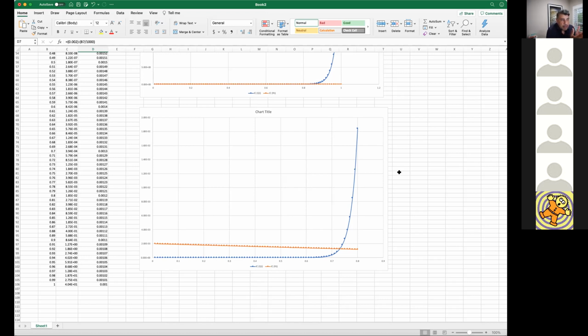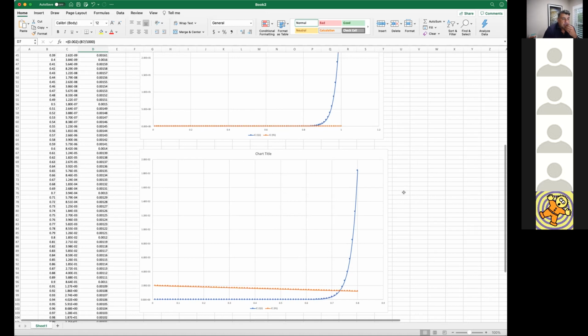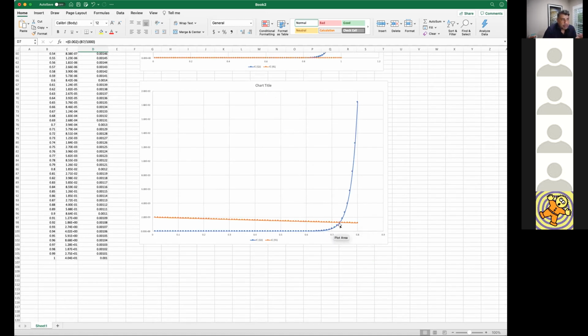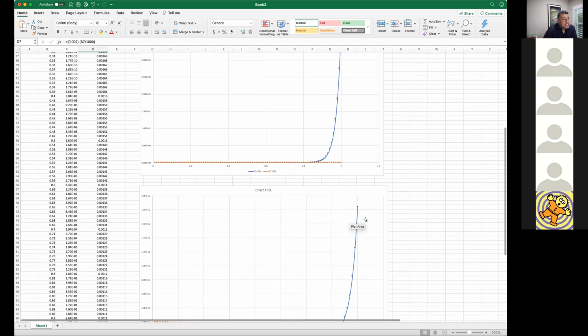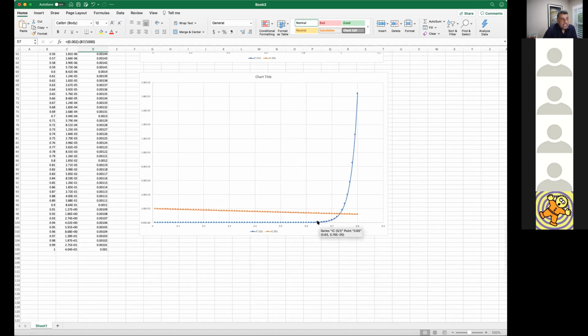So again, I'm hoping that this graphical model makes more sense for some of you. I wanted to show you what we're doing in terms of numerical analysis, and also, because I keep drawing this exponential curve, from this you really see why our initial guess for VBE should be between 650 and say 800 or 850.